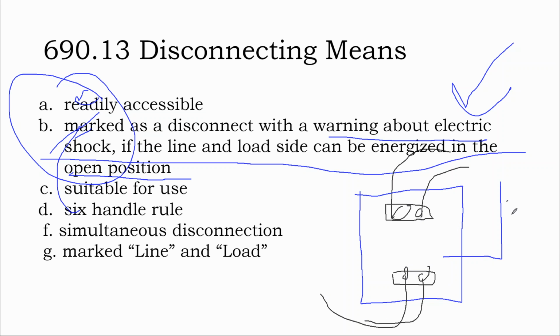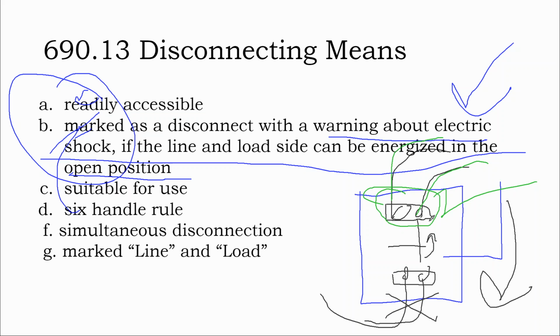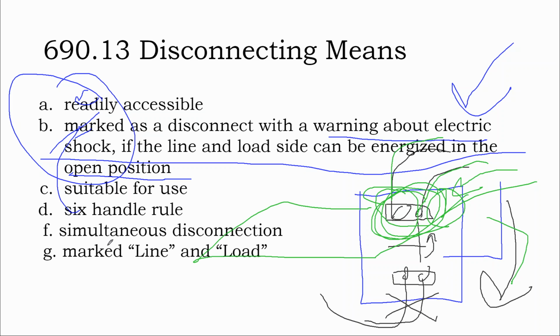And you turn this disconnect switch off. What it's going to do is there's a connection point between these two circuits, and when you turn it off, it lifts that connection point upward and it kills power to the solar array, so the solar array is disconnected. The problem is you still have live connections coming in from the grid. So these terminals, even though the disconnect switch is off and this switch is open, the faceplate's up, these terminals are exposed, these terminals are still hot at the very top.